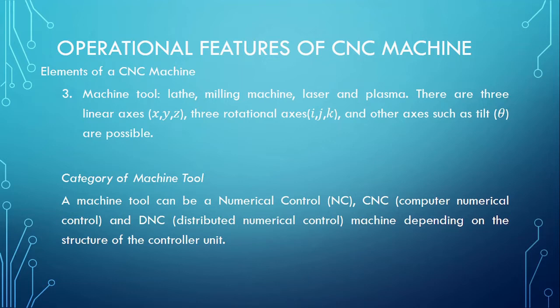the conditions of the machine in terms of their work rate, in terms of the scrap rate, in terms of the working process, in terms of production rate and all of that, which is not possible with just a CNC machine. So the difference between the DNC and the CNC is that the CNC machine does not have feedback, whereas the DNC machine has feedback, and the DNC is just a network of CNC machines. So that is the difference between the three.